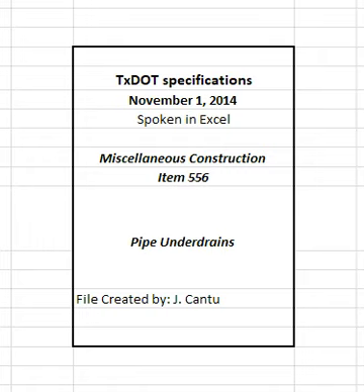2. Materials. 2.1 Pipe. Furnish the types and sizes of pipe specified on the plans. Use only one type of pipe for any underdrain system on the project. Use perforated pipe in areas to be drained, and use non-perforated pipe between the perforated pipe and the outfall.